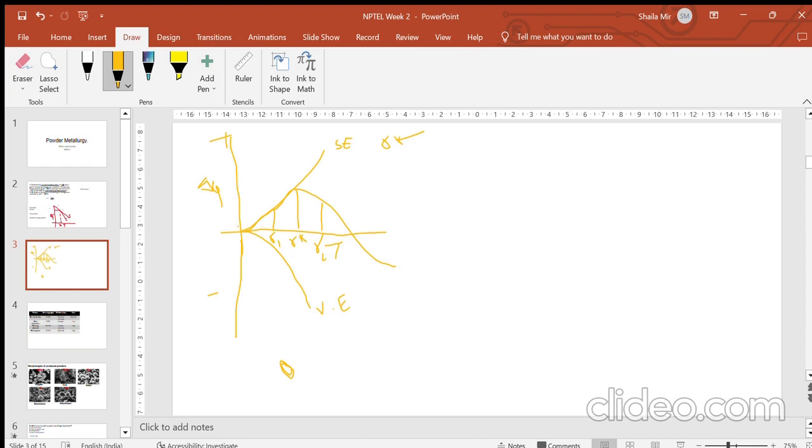So certain nuclei might have solidified out of the melt, but after a time these solidified particles shrink or get back to the liquid melt, because they are not at the ideal Gibbs free energy position. Similarly, if we have a radius R2 that is greater than the critical radius, this particle also has to decrease its Gibbs free energy and achieve an optimal condition.